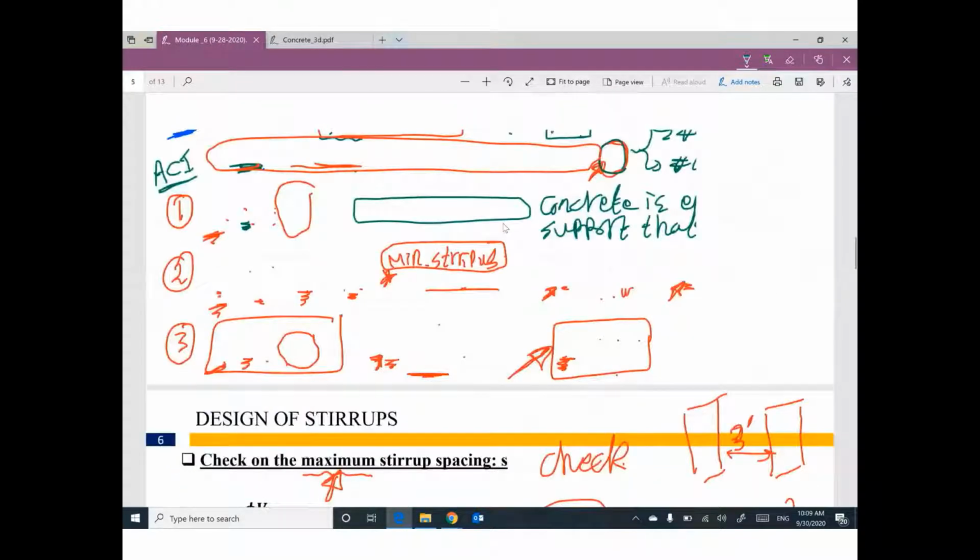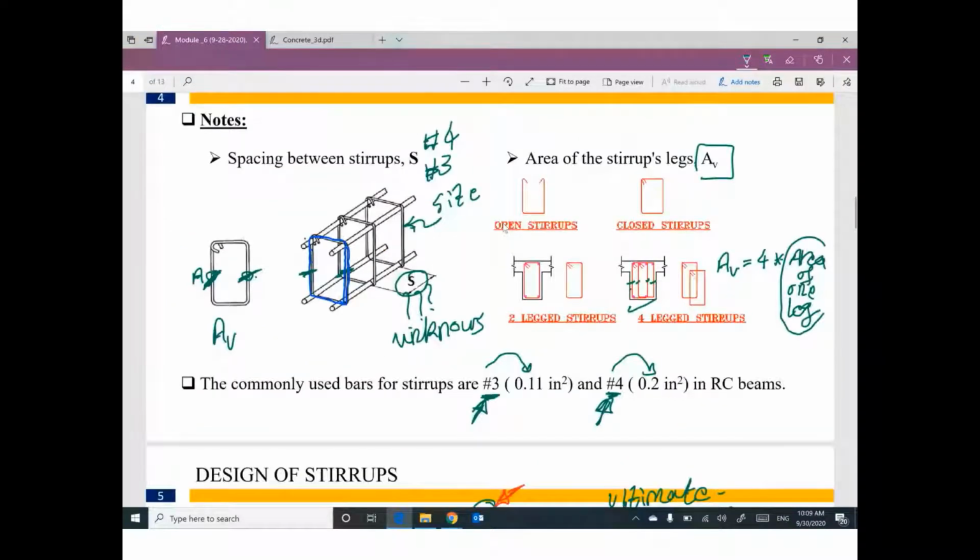as you go back to the actual shape of your stirrups. Can you watch this one? We are looking to deform the bar to take this rectangular shape. If you have a large size of bars, probably your bars will be broken if you make this right angle.